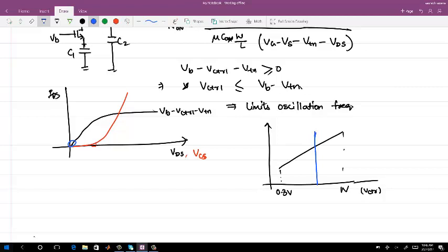But if the control voltage is getting limited, you are always limited on the other side. This is the case where your frequency saturates after a certain control voltage. So the negative feedback loop cannot take care of anything. It means how much control voltage can you raise? You have to change other parameters to get the desired frequency.